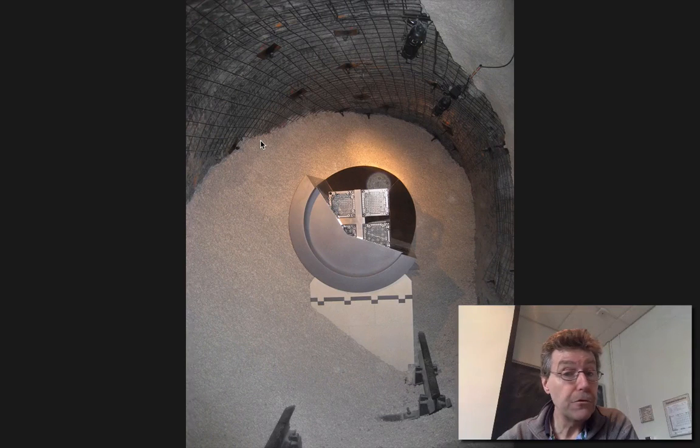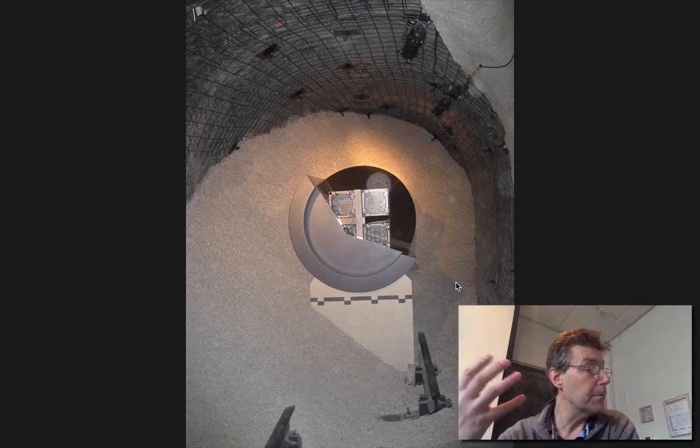and also to do full-scale experiments where you take an assembly of, not real in this case, reactor rods, the fuel rods that go into reactors, place them in an array, place them in a cask, and then put that cask within a tunnel, and then backfill this tunnel with bentonite, and that would be the form of a typical repository in some of the European programs.